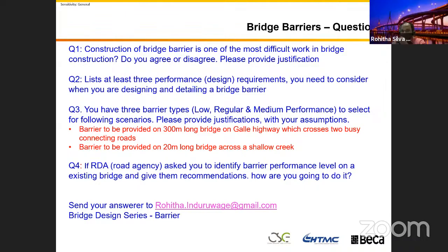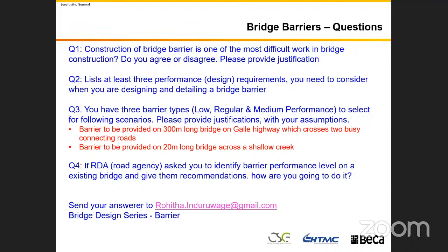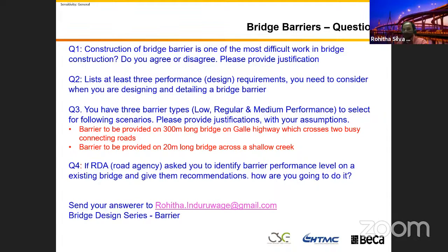But some of the piles, we actually had some issues when we did integrity testing and other things, because of this continuous construction, they did it in one go. The method is you put the casing in and then auger down and fill with bentonite, and then they pour the concrete, flushing out the bentonite. Then we do the integrity test, the comprehensive one. It's not like a hammer test. The sonic logging test. I have that information. Maybe I can send it to you.